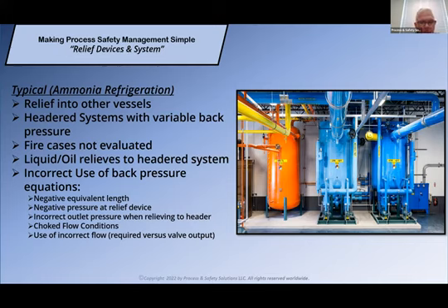Headered systems have variable back pressure. And we see this quite often where you have multiple relief valves relieving into the header, but there was no consideration given for the fact that you could have multiple relief valves relieving at the same time, affecting how other relief valves in that system can relieve as well.